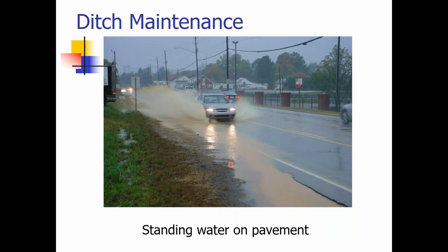Here's an example of some standing water on the pavement. And again, if you look at this area, you have a sort of a ditch area here, but it's not keeping the water back. There's so much of it, and the grade that it is, the water's coming over and it's sitting. And if you'll notice this area right here, and we talked about this at length on Tuesday, there's a drop off right there. And that open area, until it's filled, is going to collect with water. Water will fill that area, and you're going to end up with a situation like this.